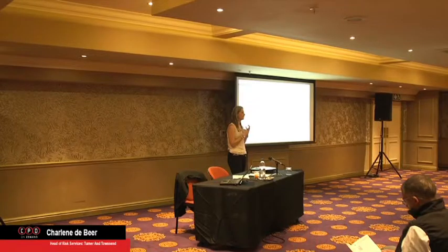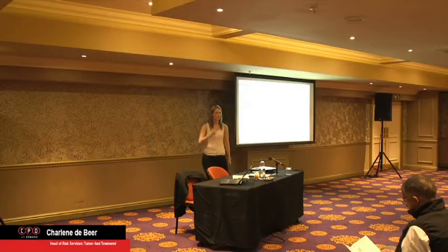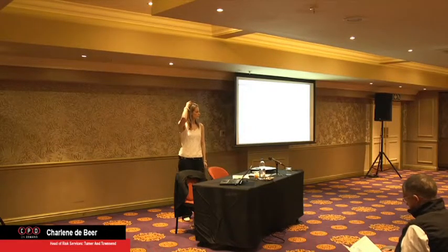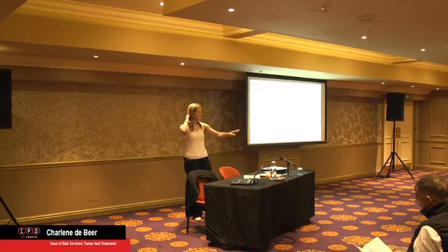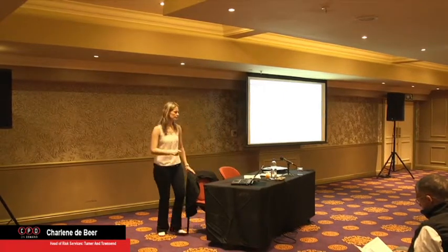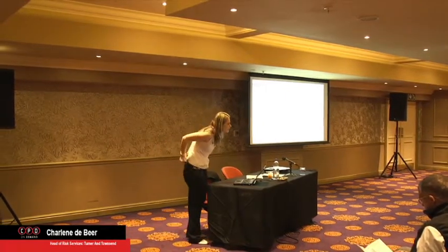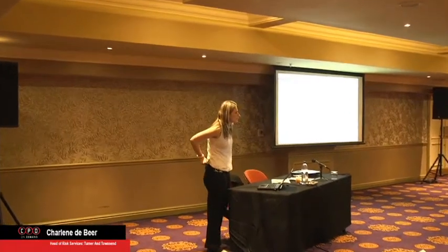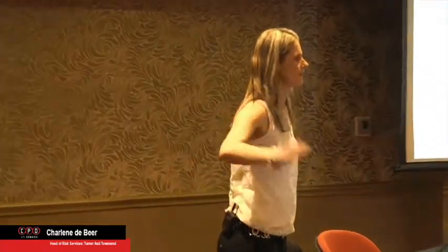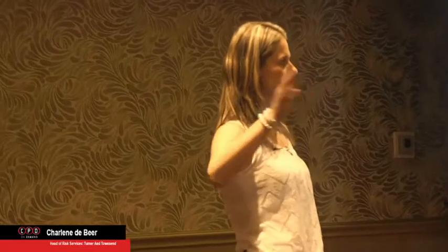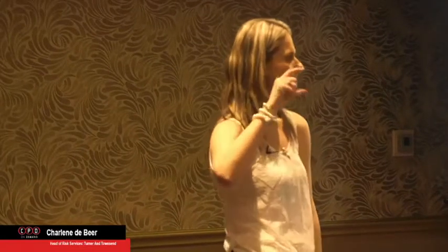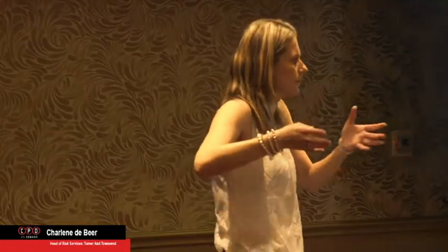And that's why I said it has to have logic. You have to explain to them why you're saying it's that time and that cost. So from a schedule point of view, why I would interrogate a schedule before I would risk load it is, if it has open-ended activities, it won't run the date. It won't have any end date. It throws out this funny hash sign. It just can't establish a date because it doesn't know where the MC or the commissioning date is.